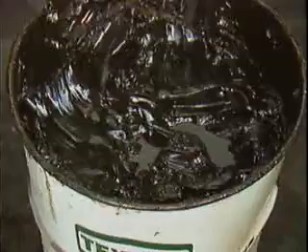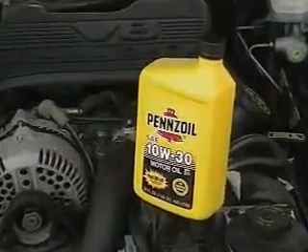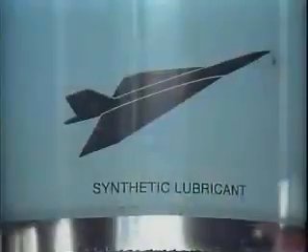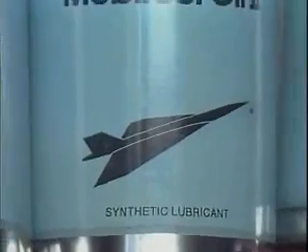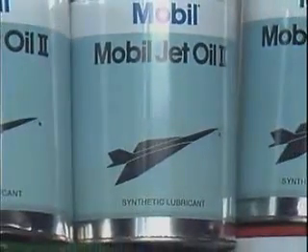Three common kinds of lubricants are liquids, greases, and solids. Liquid lubricants are oils. Mineral oils, which come from refined crude oil, and synthetic oils, which are man-made compounds, are commonly used in industrial applications. Greases aren't strictly liquid or solid. Instead, they typically soften when the temperature rises and stiffen when the temperature falls.